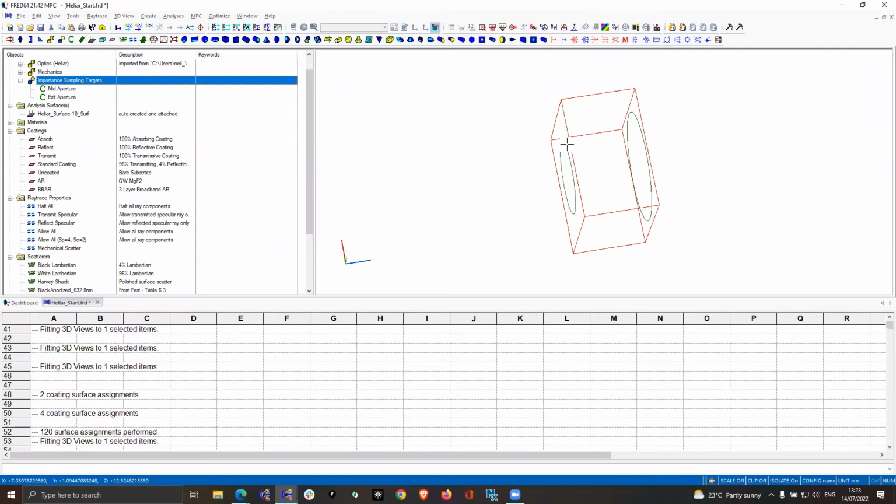And we're going to use these curves to define some important sampling that says that the surfaces at the front of the optical system that can essentially see this aperture or this opening will preferentially scatter rays into this opening. And similarly, in the second half of the optical system, the surfaces that face this opening will also scatter light preferentially through that opening. Okay, so those are the 2 targets that we're going to choose, and anything other than that is just going to be around specular.